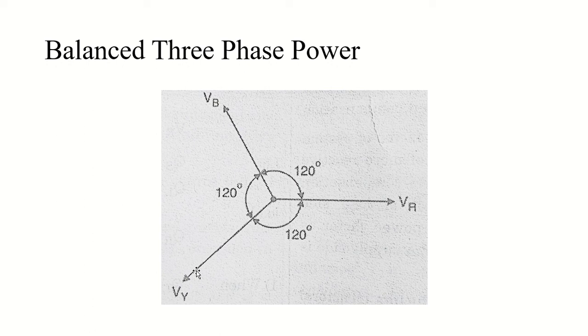So because of this diverse nature of the load, we are having external compensating devices which we have seen just a moment ago, like shunt capacitors or shunt reactors or synchronous condensers, right? These are external compensation devices which we use to maintain the power factor, and to keep our three phase system in balance, three phase power in balance. So that is the balance of three phase power.